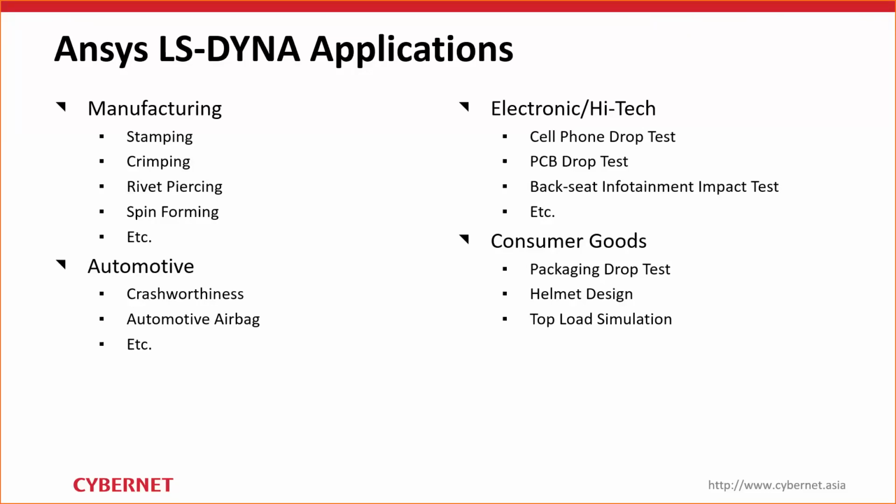When we talk about drop tests, we need to identify the structural behavior during and also after the impact, so after our device hits the ground or the floor. That means any sudden contacts or any large deformation or large plasticity that happen rapidly need to be taken into account. For this kind of analysis, explicit dynamics is actually the best way to go.